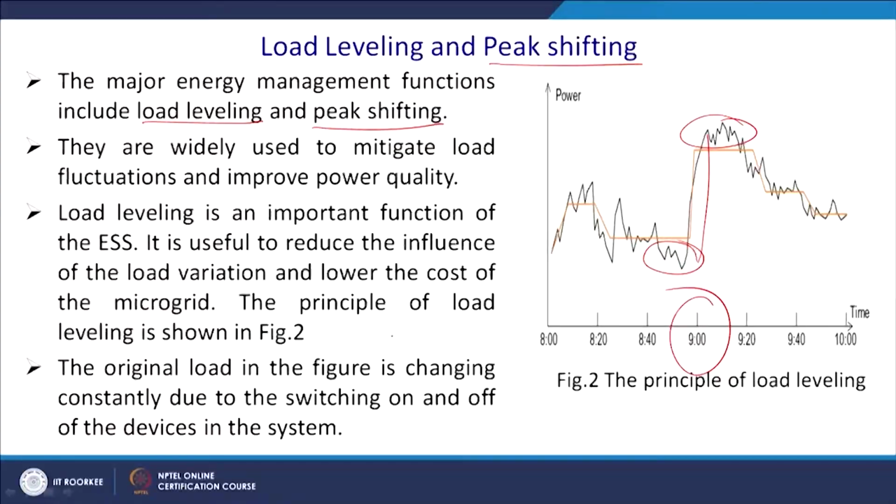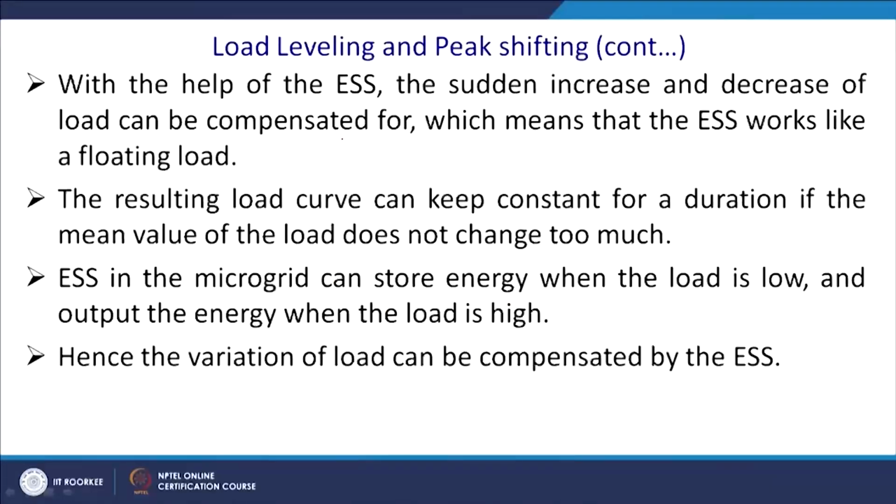The principle of load leveling is shown in this figure. The original load in the figure is changing constantly due to the switching on and off of devices in the system. With the help of the ESS, the sudden increase and sudden decrease can be compensated for, which means the ESS works like a floating, bipolar load. It can be positive or negative: it may absorb power or give you power.